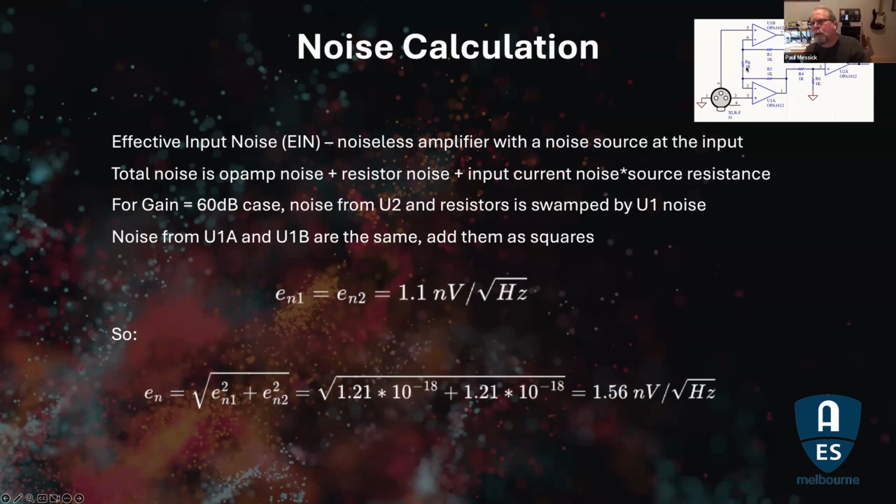But as RG goes to 0, these are just shorted out. And so they effectively don't add any noise. So you actually can see the noise floor of the amplifier at 0 dB gain, it's up here. And as the gain goes up, the noise floor goes down. Very beneficial.